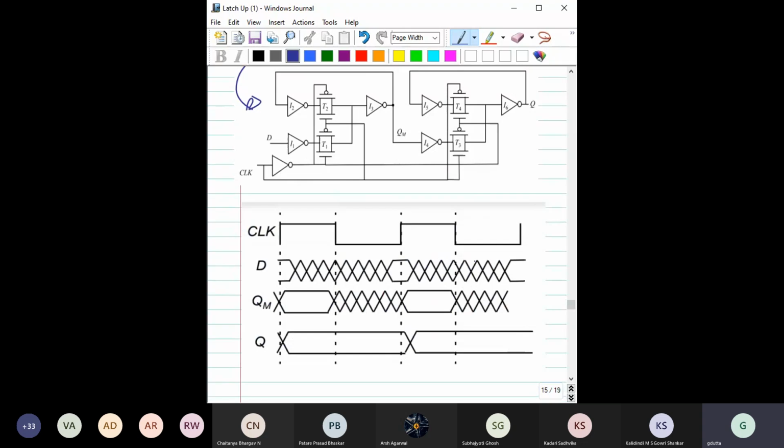see this one, you will understand from here. This is the clock input, right? And this is the D input, this data input. So the question is, during this positive edge of the clock, before that, for some time, this data has to be stable. Can you see this? Before some time, the data has to be stable. After this clock edge also, this data has to be stable, right? Do you agree with that from this? Now, why so? We will discuss the reason.